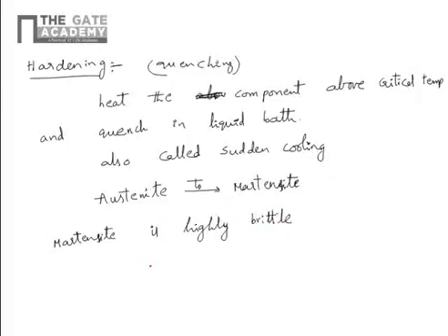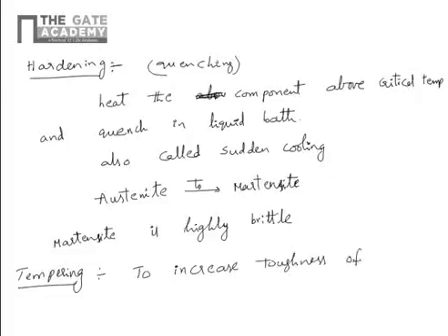So to reduce the brittleness and to increase the toughness or ductility, we again do tempering. Tempering is to increase the toughness of the hardened component. So tempering we always do after hardening. A question came once: is tempering always followed by hardening?